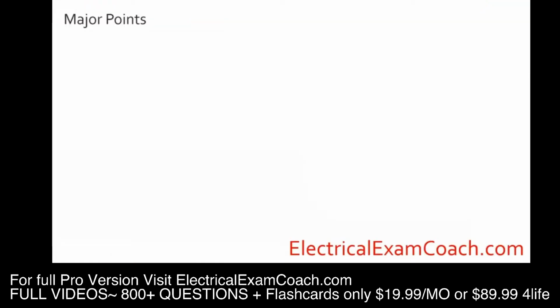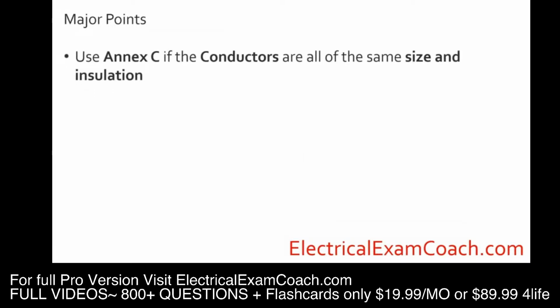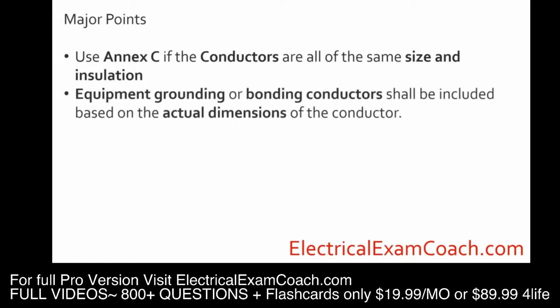Before we jump into the practice questions, let's go ahead and hit the major points. We're going to use Annex C when all of the conductors are of the same size and insulation. When dealing with equipment, grounding, and bonding conductors, they shall be included based off the actual dimensions of the conductor. It's not like we did in box fill. If there is a grounding conductor in that pipe, it counts 1 for 1, and all of them count. If you've got 10 of them, they all count.